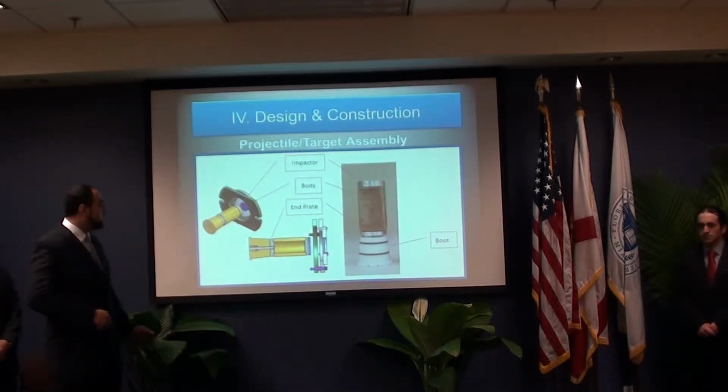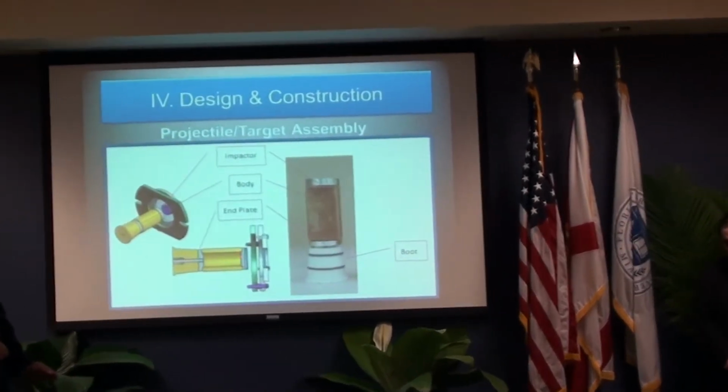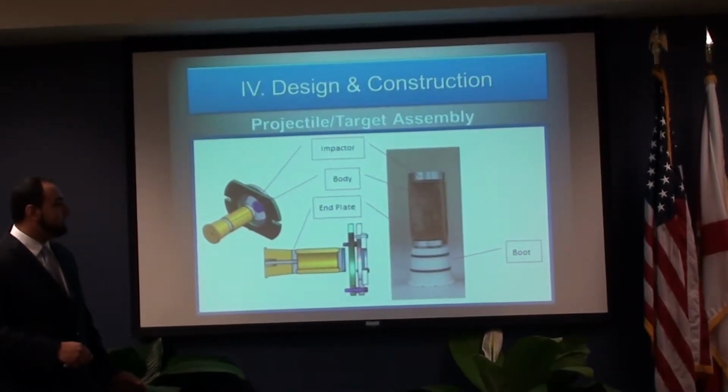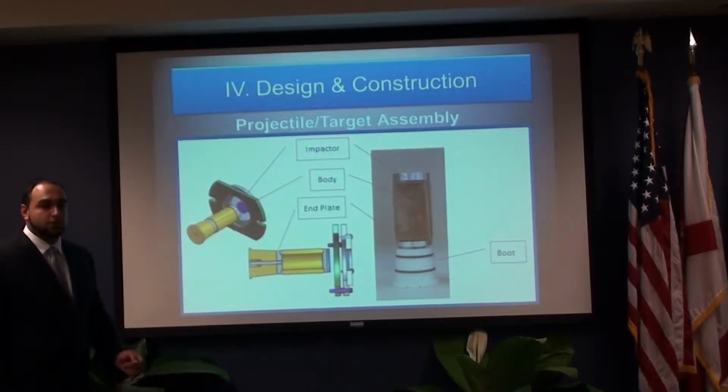Okay, here's a diagram of the actual experiment. We have the projectile coming downrange from the barrel of the gun. It is a powdered gun. Here's the impactor in the front, of course variable thickness and variable material. It makes planar impact with the target that's encased by a momentum trap, and then it's released into the soft catch recovery system for further analysis.